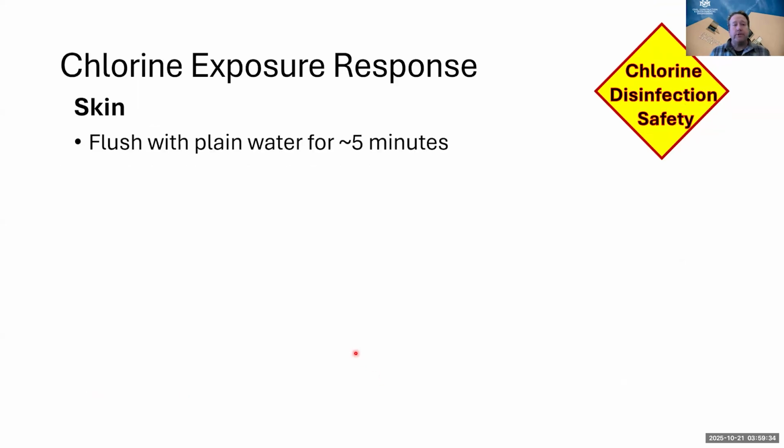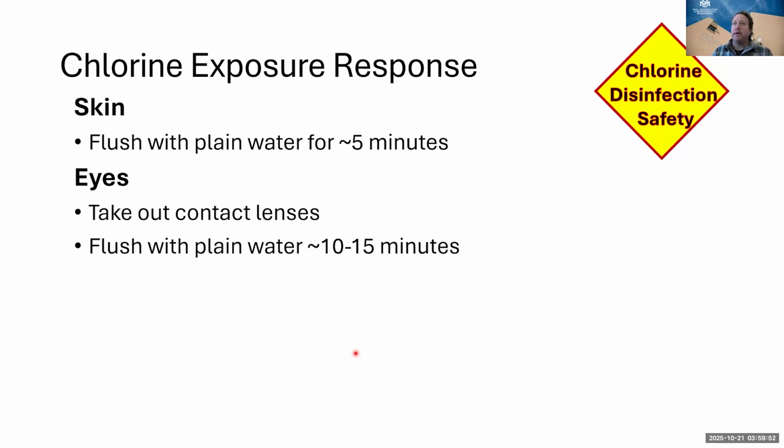So, what should your response be if you have these types of exposures? So, with skin, you want to flush with plain water for about 5 minutes. You might not realize you get it on your skin, but if you feel like a slickness to your skin, you may have gotten some chlorine on it. So, you want to flush it off.